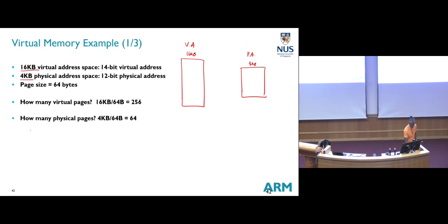My entire space here is 0x0000 to 4000. The total space is always 0 to 1 less than 4000, so the ending address will be 0x3FFF, because 4000 in the total space starts from 0, so the ending is 1 less than that.